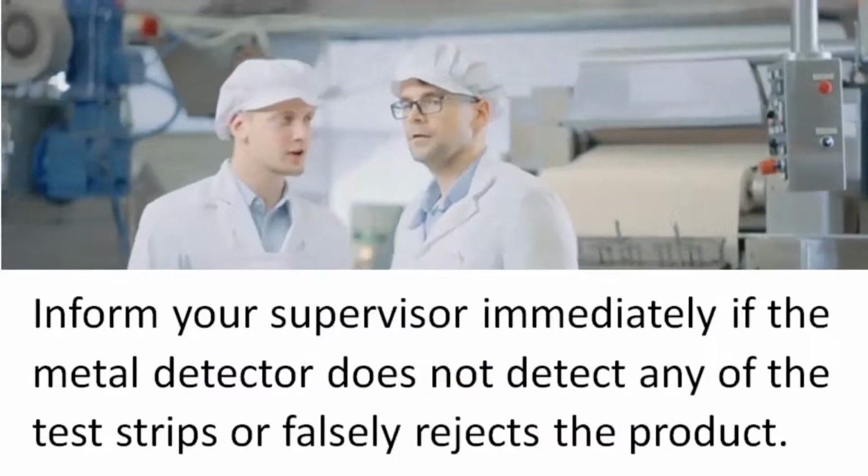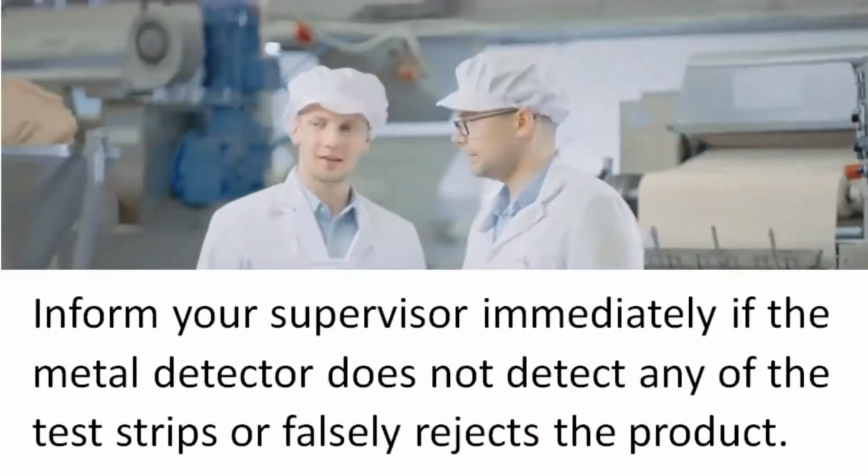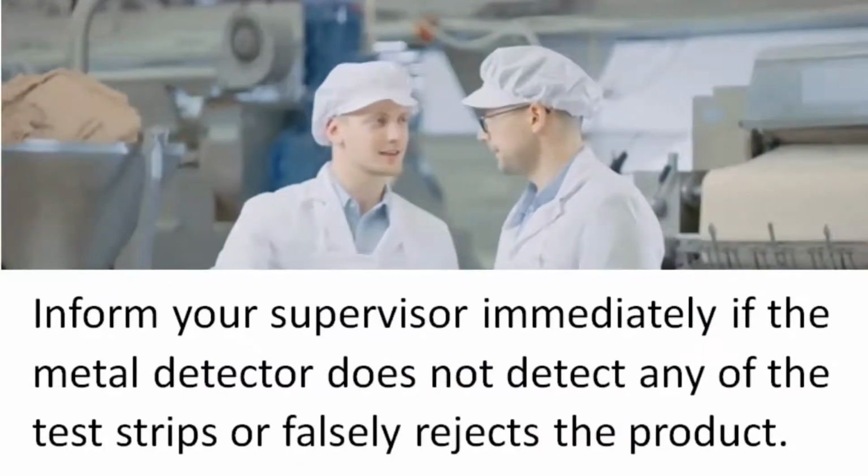Inform your supervisor immediately if the metal detector does not detect any of the test strips or falsely rejects the product.